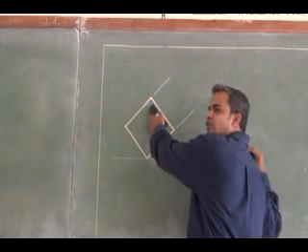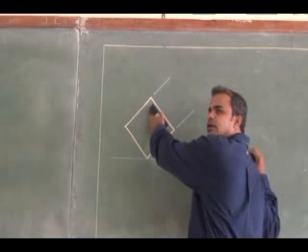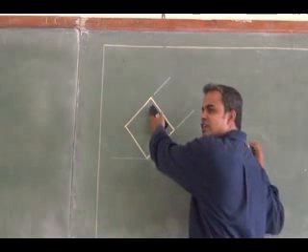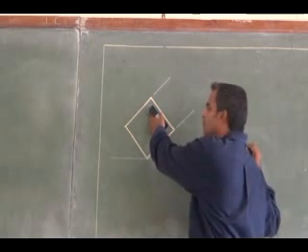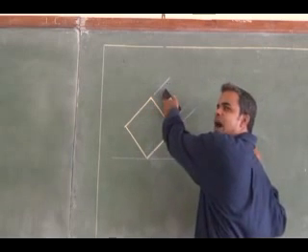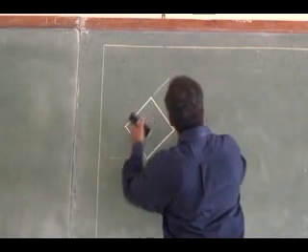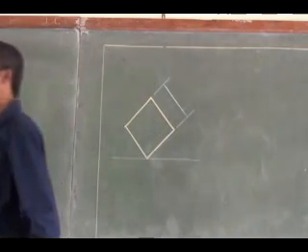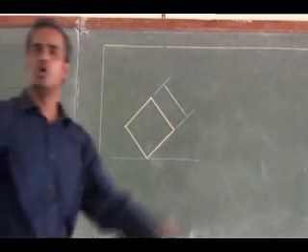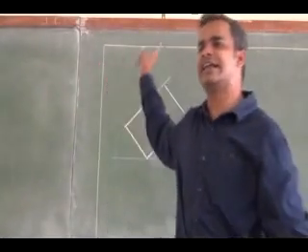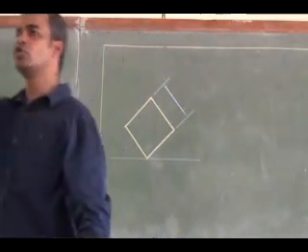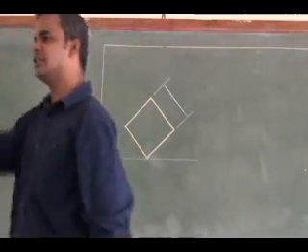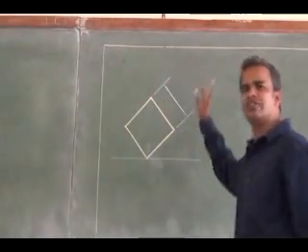So then, on which scale you have fixed the geometry, using that scale of your drafter, I can move it 10 mm away and I can draw a parallel line. That is called the dimension line. So for this extension line and dimension line, you have to use your drafter. See, this is white, it is 2H.